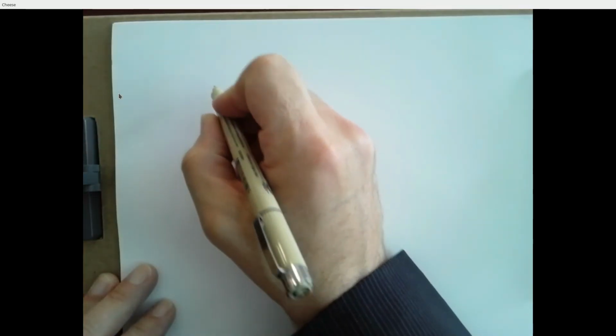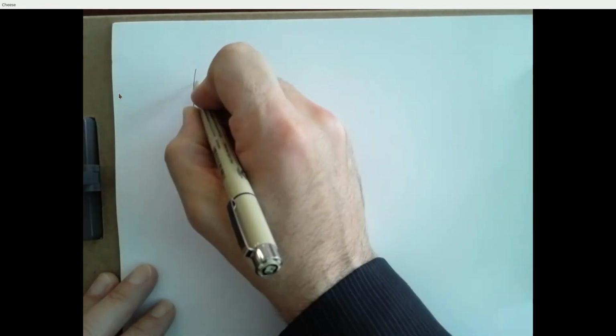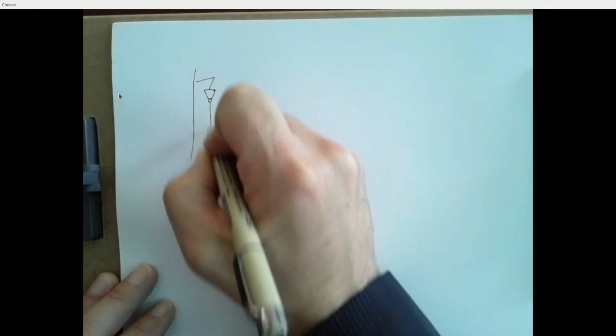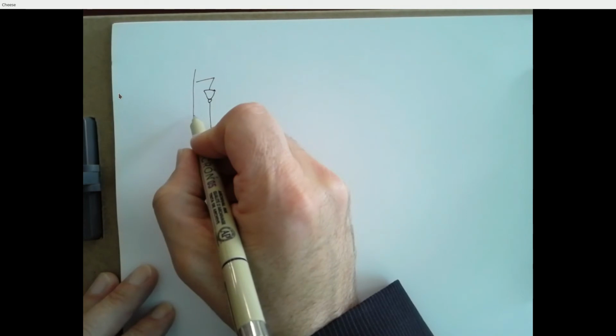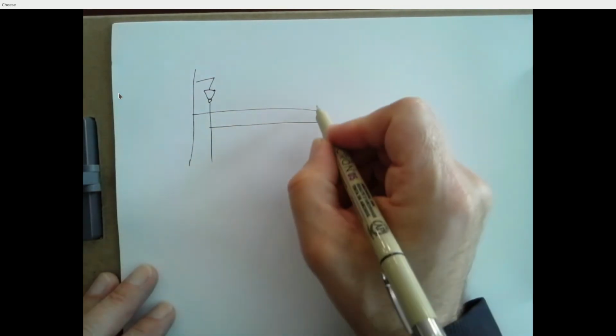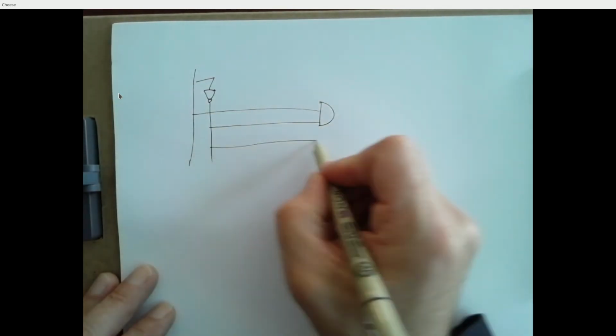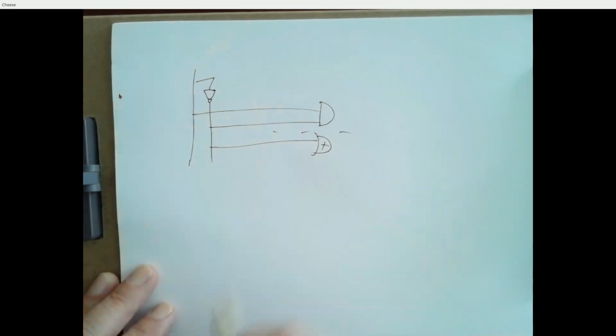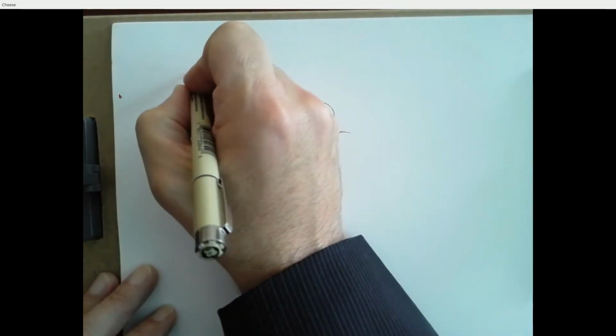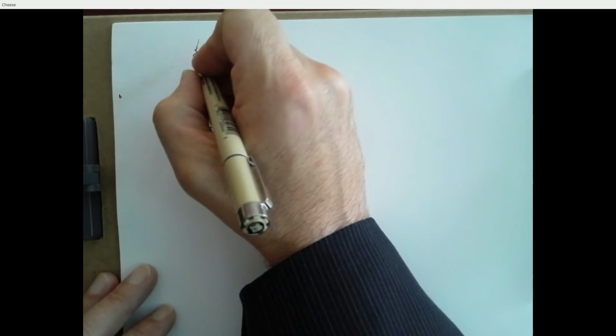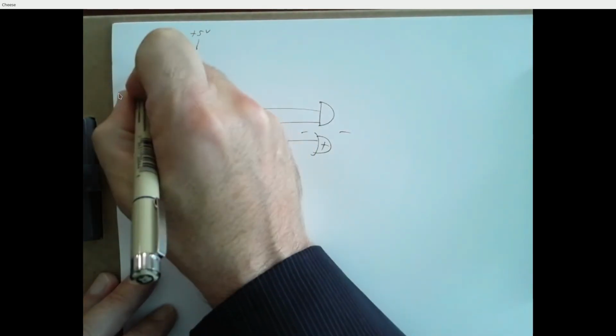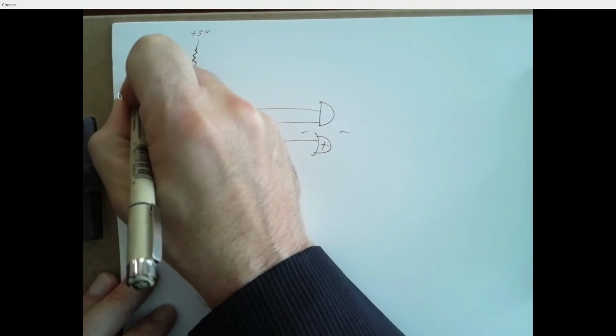I didn't take off points for this, but I noted it on most people's schematics. Let's say you're drawing a circuit and you've got some input A and you've got things coming off of here and going into gates, and you've got a switch. So remember how we make switches. You put a 1K resistor, you wire it to 5 volts, and then we have a switch that can connect this to ground.